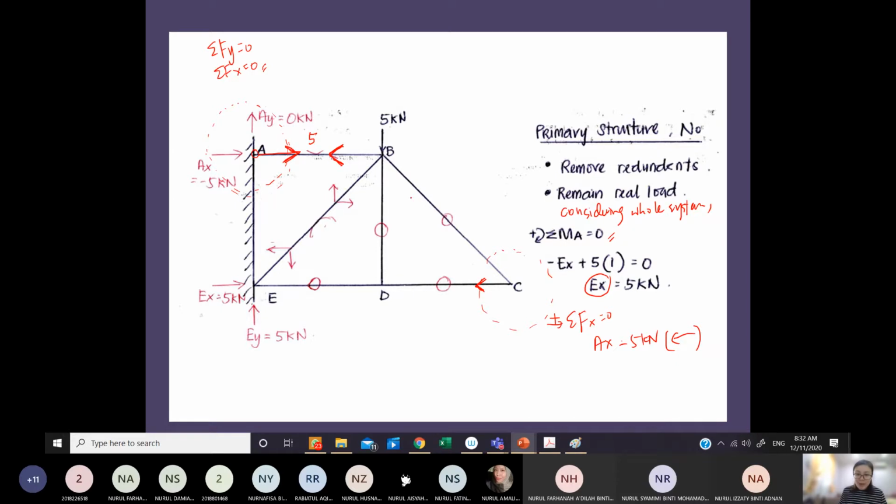And then I will have another horizontal force resolved from this member CB, and one vertical force resolved from my member CB. I directly resolve it in horizontal and vertical only so that I can use this quickly. So now I have only one vertical unknown at this joint C.